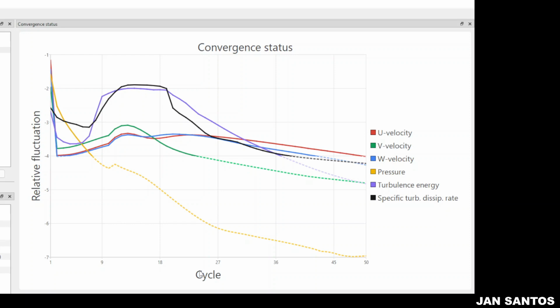So, most relative fluctuations are at or below -4. Okay, or yeah, here. Those are going to be what's most relative. As you can see, they are dashed. If you can notice, even down to our red line here, it is starting to be dashed since it entered below -4. Okay, so it is a typical threshold in CFD to consider results stable.